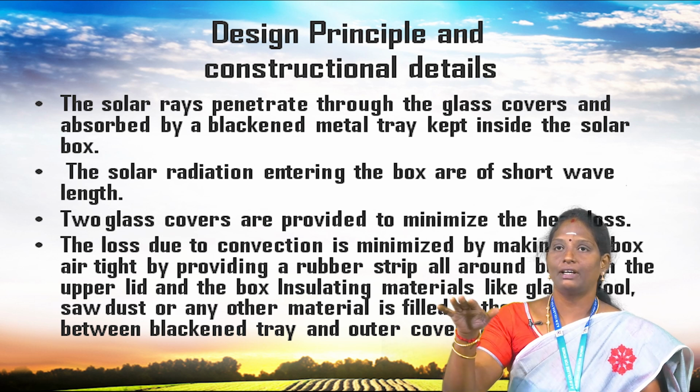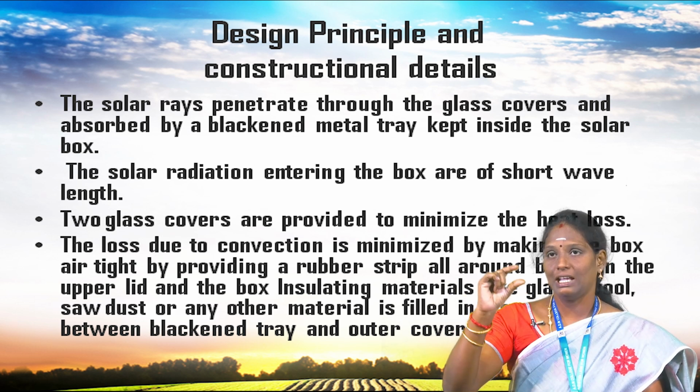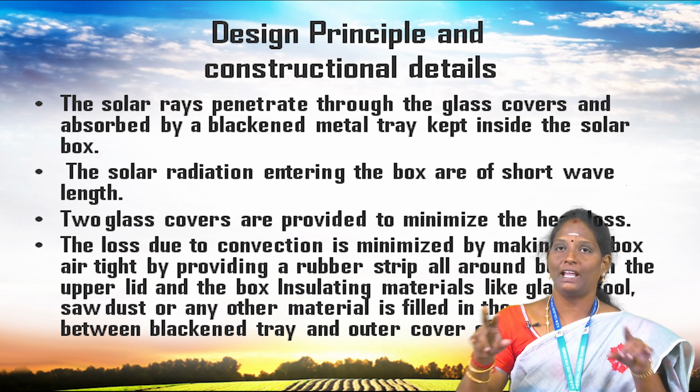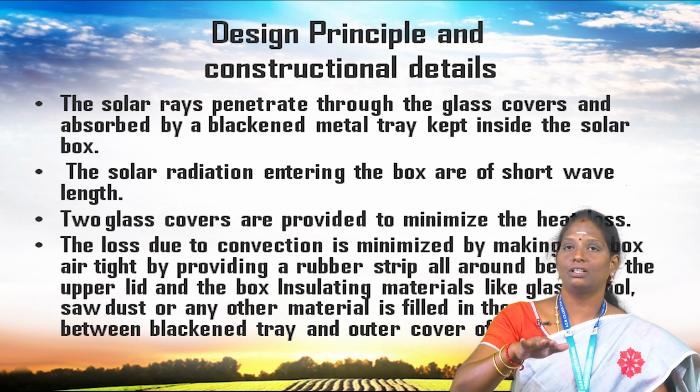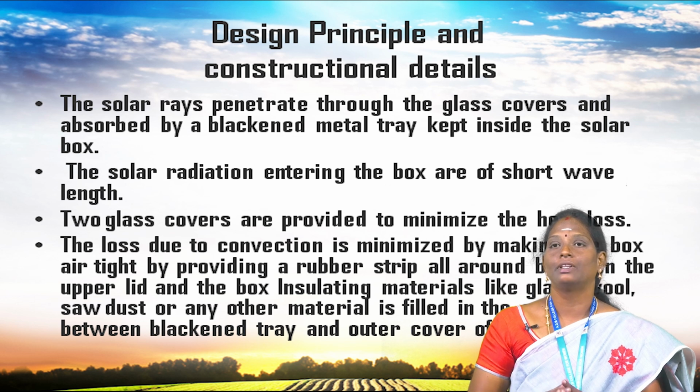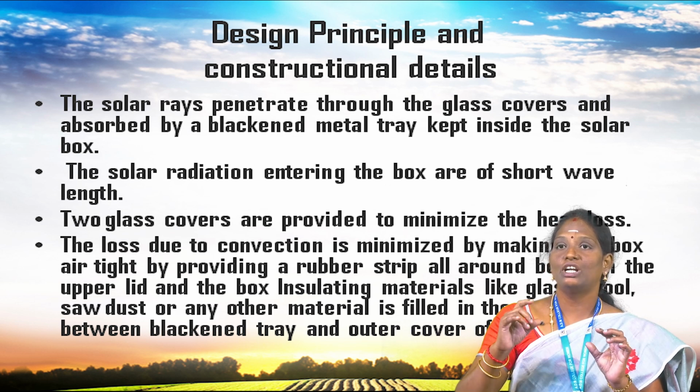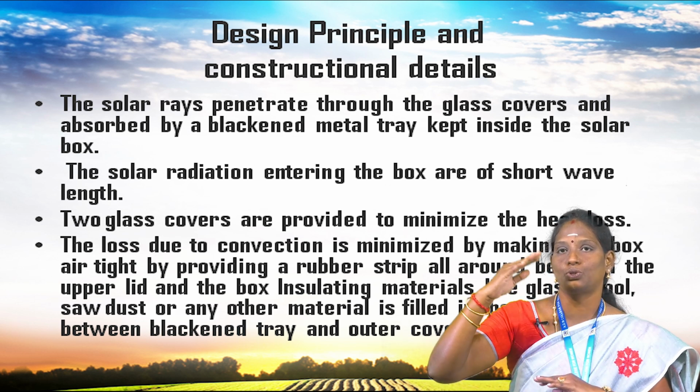The top cover contains two plain glasses, 3 mm thick, fixed on a wooden or metal frame, keeping about 25 mm distance between the two.